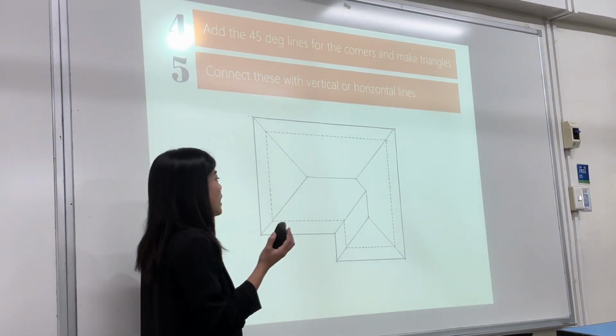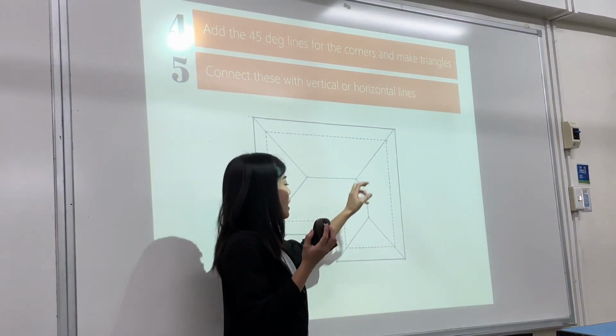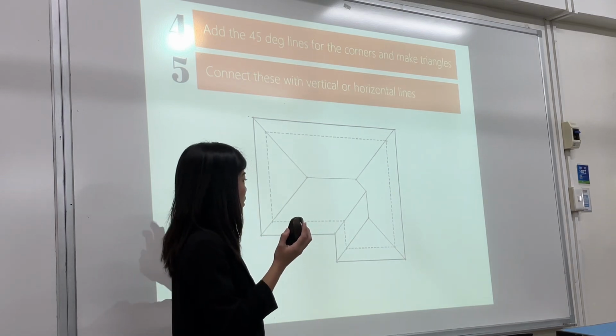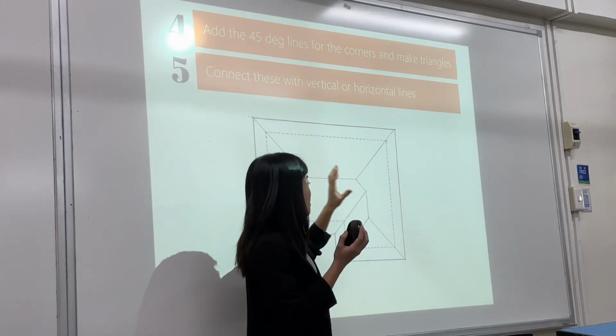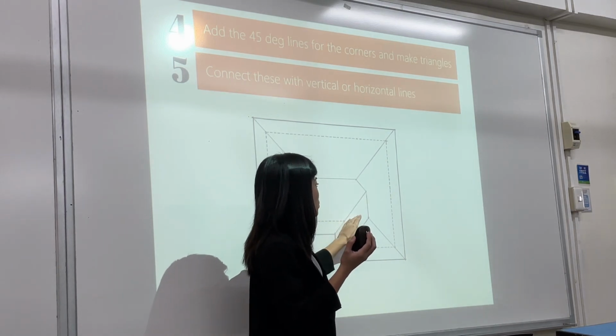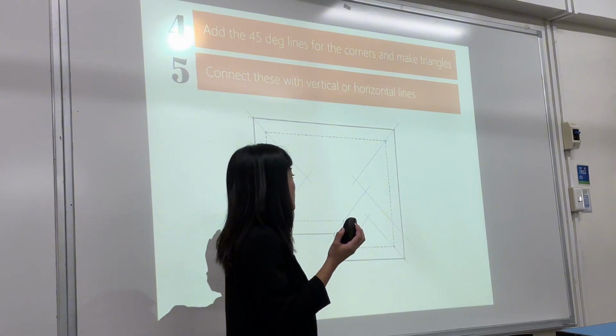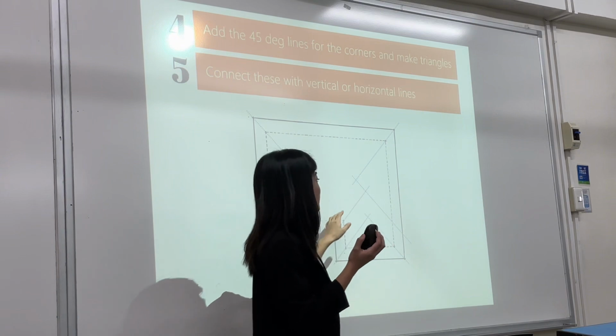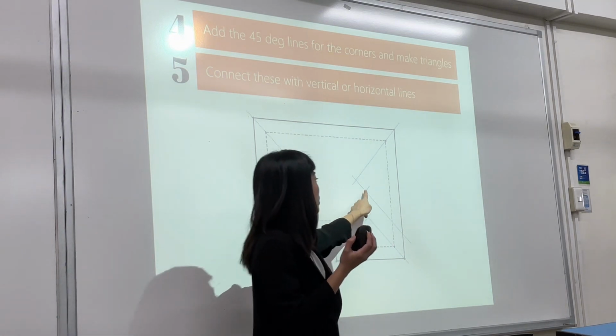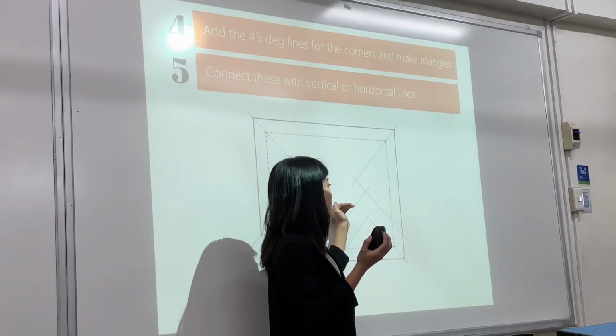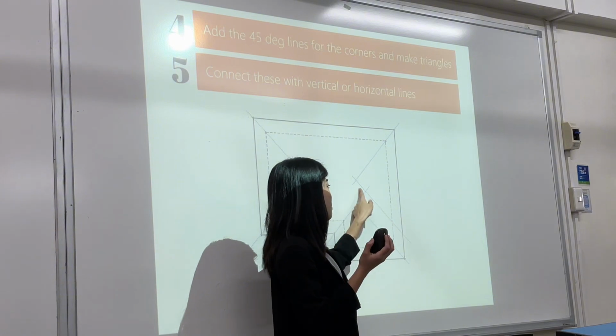So, in reality, ito yung parang kanal, I don't know what's the formal name. But di ba, ma-imagine nyo na may kanal siya dito. So, bakit natin tinanggal ito na line? Common mistake, kung ano talaga ang guideline, ginagawang solid line. So, you have to remove this one. Kasi in reality, anong purpose ng line na yan? Wala, di ba?